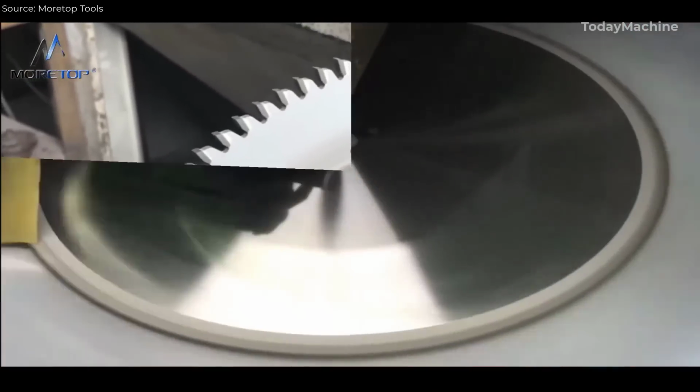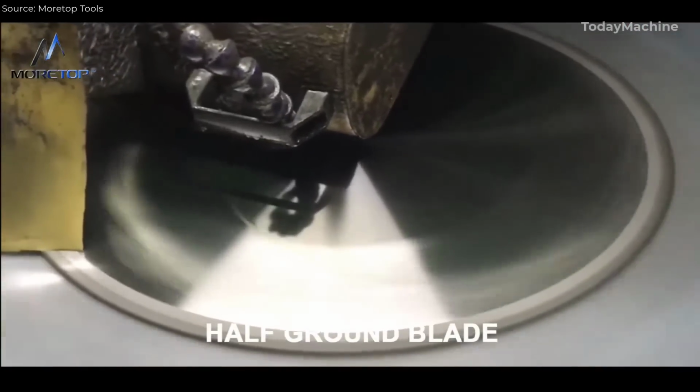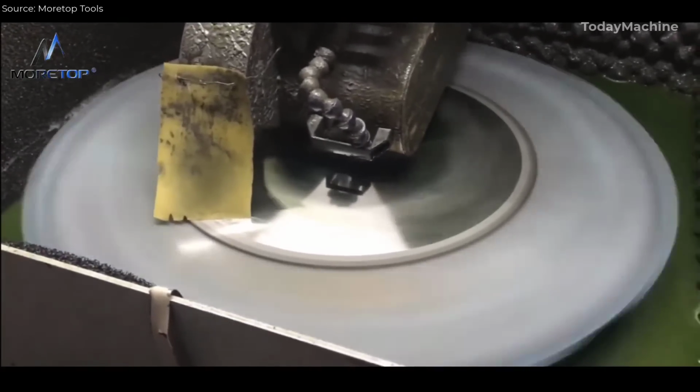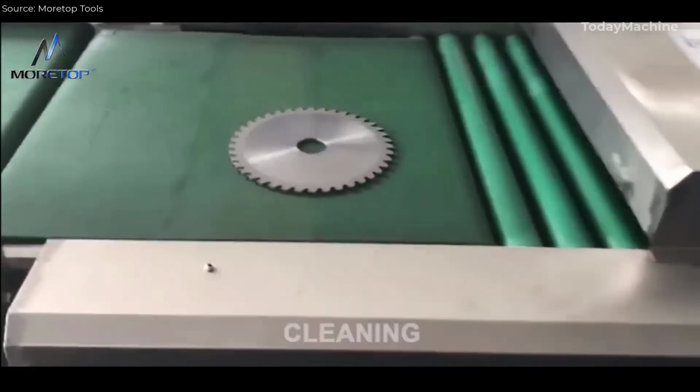Furthermore, the use of advanced coatings such as titanium nitride, TiN, or diamond-like carbon, DLC, has increased blade durability by reducing friction and heat generation during cutting. These coatings can extend blade life by up to 50%, making them more cost-effective in the long run.